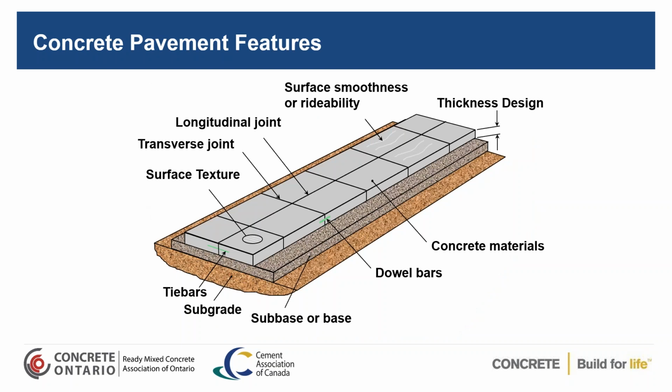So the next slide is just to review what the key components of a concrete pavement are. Well, we learned in the Municipal Concrete Paving Association there's a big difference between a tie bar and a dowel. Tie bars are deformed 15M, 750 millimeter. They have ribbing on them, and there's no oil or ductile coating put on them to prevent a bond. You want the concrete to bond to that, so that the longitudinal joint will not drift apart and become a maintenance issue. Dowels, on the other hand, are 32 millimeter, 38 in thicker pavements.